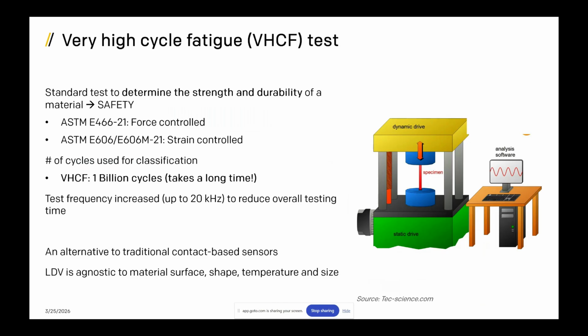Well, classically, you can do that with a strain gauge just by attaching a strain gauge to the point of interest on the material specimen. But what if you also want to heat up the sample at the same time to see how that affects the test? A strain gauge probably won't survive that. Or what if the number of cycles is so high that the sample itself outlives the lifetime of the strain gauge?